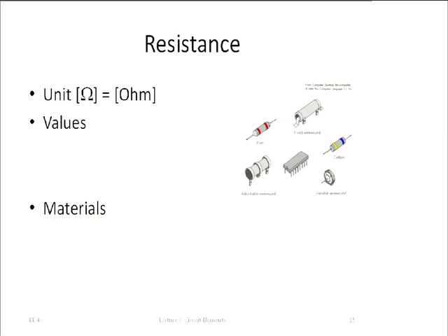Yeah? I don't understand. Why is the problem if it has a high resistance and you're handling it? So let's assume that this was our resistor here, and its value was, let's say, 1 gigohm, so 10 to the 9th ohm. Okay? So now you grab it and you put a film of sweat on it just by holding it.